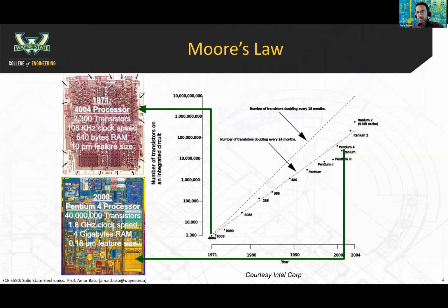Okay, what's a second order effect? Well, there are our first order models of the MOSFET, which we've talked about thus far. We've talked about the operation of the MOSFET in triode region, in saturation region, and we've talked about the energy band diagrams and the IV characteristics of the MOSFET in those regions of operation. We've assumed idealized behavior of the MOSFET. And so we're going to talk about some of the second order models, which go into more depth and consider the non-ideal behavior of the MOSFET.